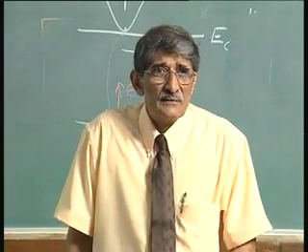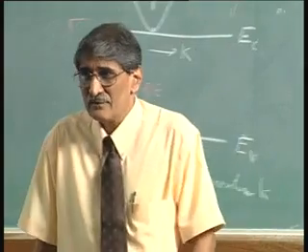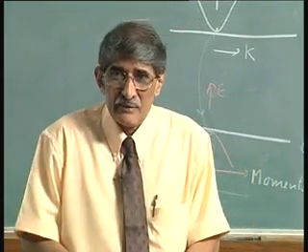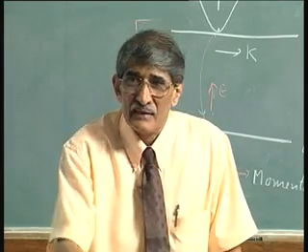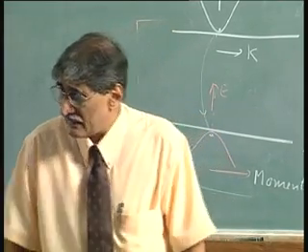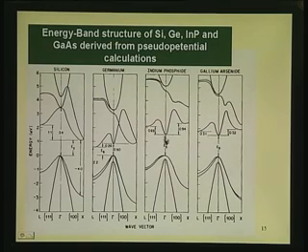For microelectronics application, it does not really matter whether it is direct band gap or indirect band gap. Those who talk of photonics, they will say I am interested in direct band gap material. Whereas, if you take say indium phosphide for example, minimum there, maximum here. So, this also has the same value. So, the gap here from here to here, what is that? That is the Eg.